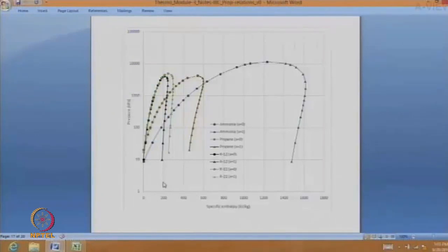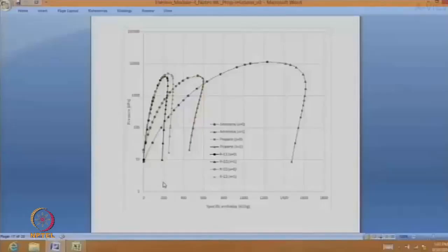But if those things are also okay, then it means that you can take the existing refrigerator or the existing air conditioner, throw out R12 and put in your new refrigerant, and your fridge and AC is good enough to keep working. And that's what initially was done. But as time goes on, we came from R12 to 22. Now 22 has to be banned and removed. So we are now looking at even more refrigerants which we can change. And that's how you see in the market today 134a in refrigerators. Five years from now, even that will probably be phased out and you will have something more coming in. And this is the basic starting point from which we do the design and engineering of all those devices.